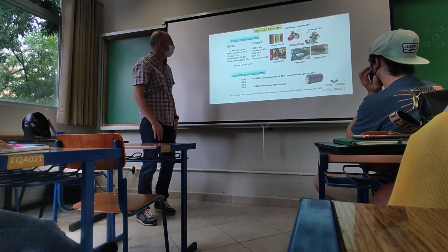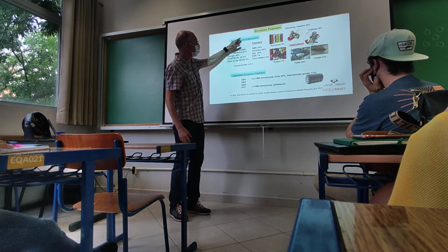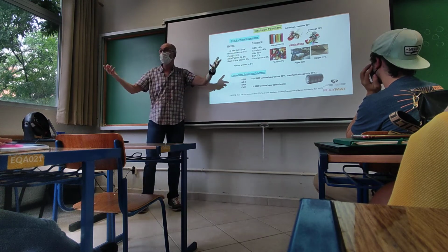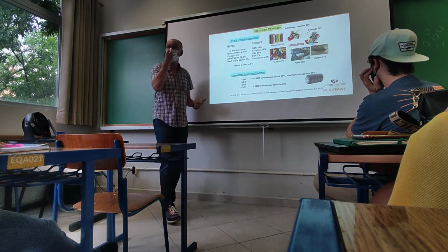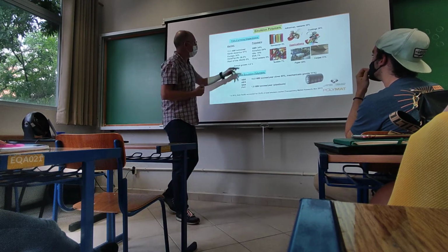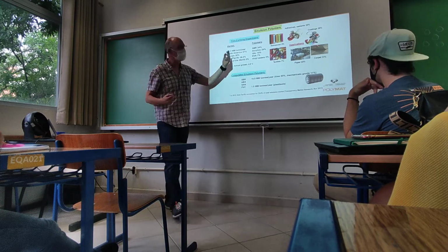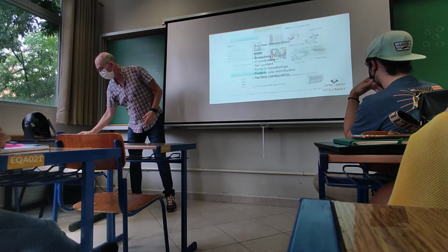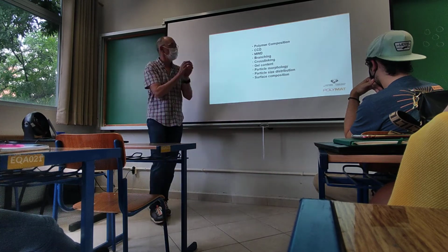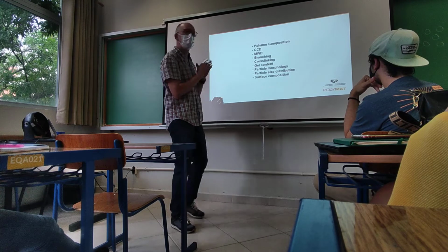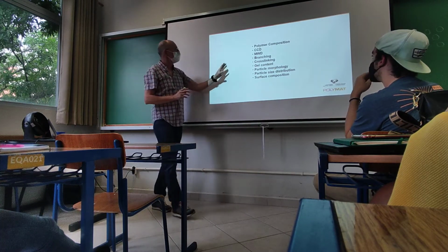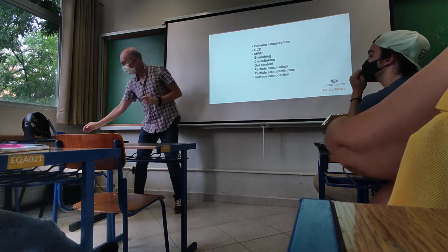It's used a lot. The polymers for the dispersions typically are acrylics, or vinyl acetate, the good glue, or the chewing gum. The chewing gum is polyvinyl acetate, okay? Ethylene vinyl acetate and vinyl esters. These are the most used polymers. Okay, so the polymers that are produced in these particles are characterized by several characteristics of the polymer. Some bulk properties, like the polymer composition.